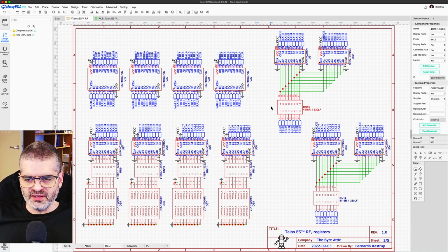You can interpret these 33 ohm resistors as a low-pass filter, because these resistances coupled with the intrinsic parasitic capacitances of the lines will give us an RC filter that is essentially a low-pass filter. And reflections tend to be the higher harmonics because PCB lines are relatively short in relation to the speed of light.